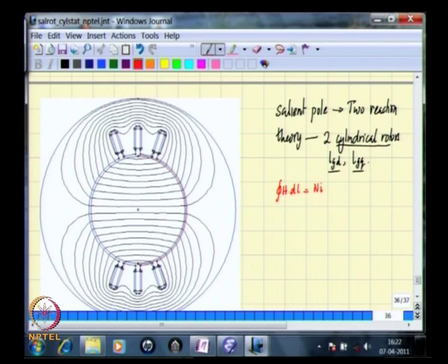So let us say we take this flux line and form our Amperian loop around that flux line, which goes like that. As you travel around that, N into I is basically the number of turns in this slot plus this slot plus this slot multiplied by the flow of current in each.